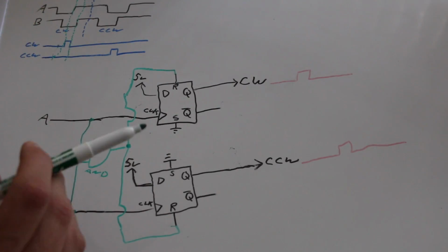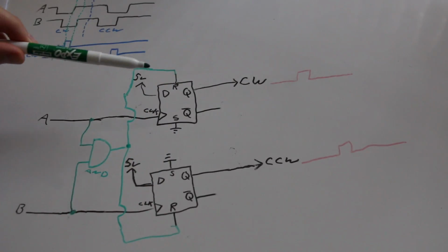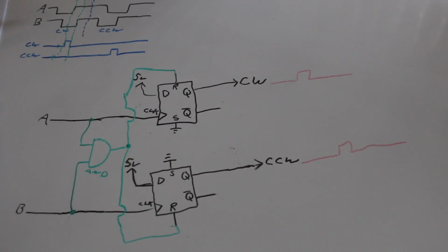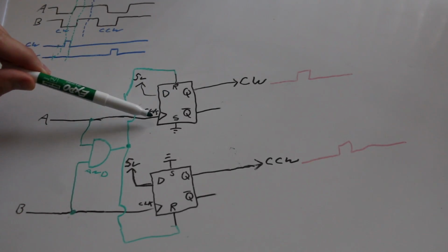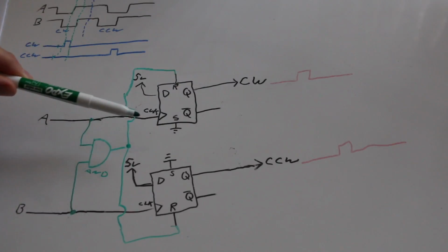And we don't have to worry about setup and hold times and coming out of reset, really, because we come out of reset as soon as the first transition occurs. We are not starting to really clock anything in until the rising edge of what triggered this thing to come out of reset.